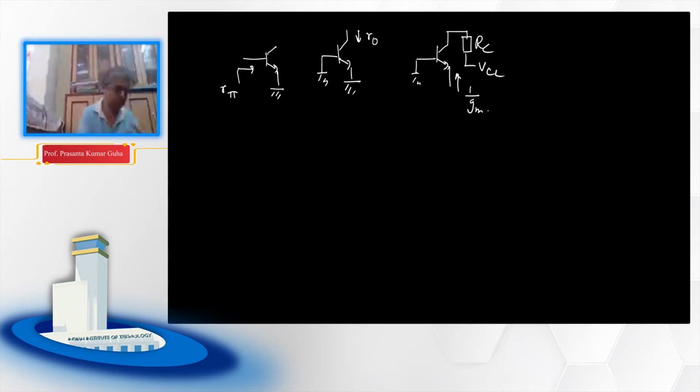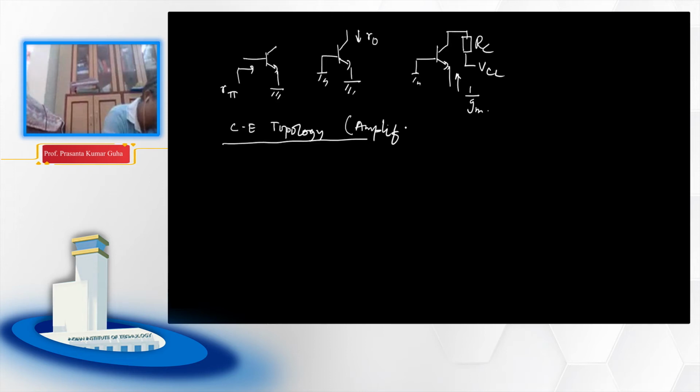We have also learned there are different amplifier topologies possible. Out of these we will mainly concentrate on the common emitter topology for the discussion of the amplifier. Now let's just concentrate on the core BJT rather than all sorts of biasing, for example voltage divider biasing. Let's concentrate on a simple BJT common emitter amplifier circuit without bothering about the biasing, and later on we can add biasing and see what changes it makes. But we will implicitly assume that it is in the forward active mode.